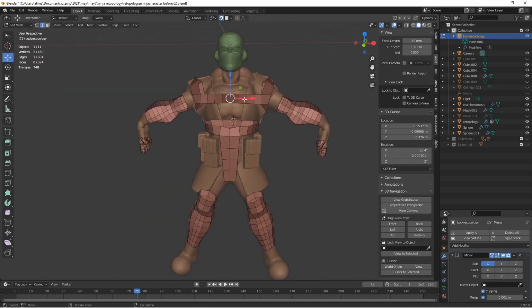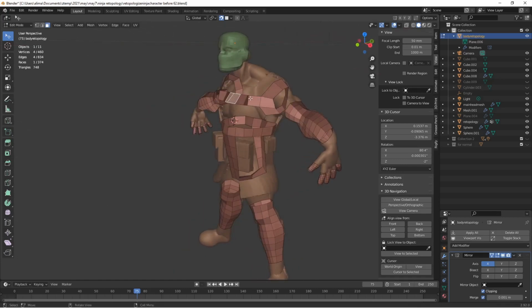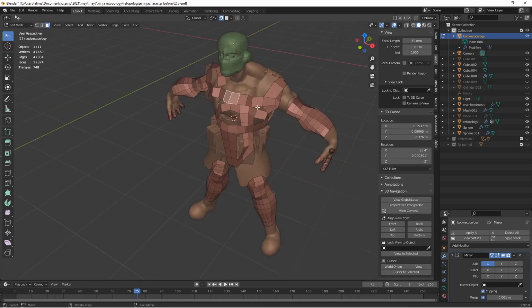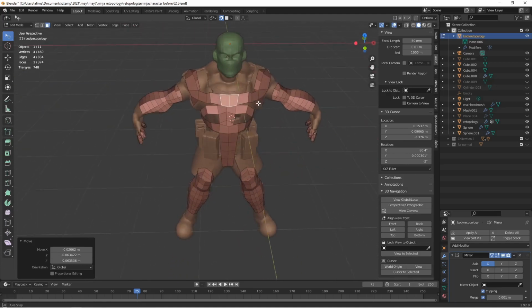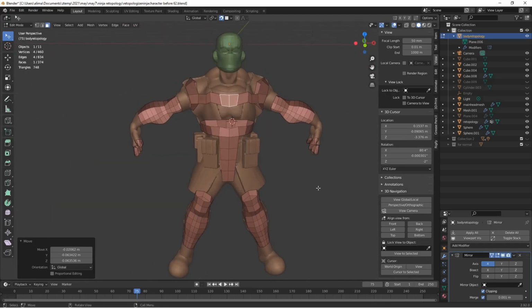Those faces aren't sticking, so we'll select here. Well, we'll go to upper left, go to face select, and by moving them slightly, there we go, that makes them actually stick. I'm going to left click to deselect. Okay, what we're going to do now is go to edge select.